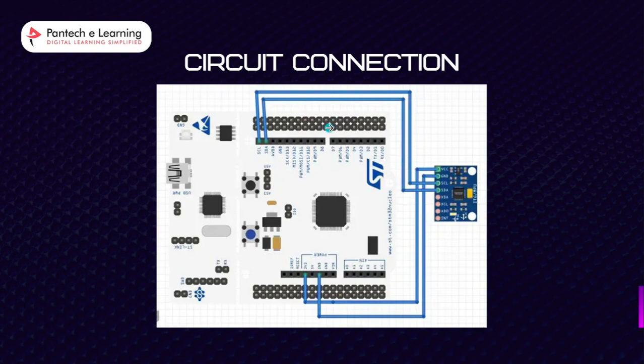And here I provide the circuit connection image. As we are using the STM32 Nucleo board, we just need to connect MPU 6050 VCC to the STM32 Nucleo 3.3V, ground to ground, and take the clock pin and data pin. You can connect them to PB8 and PB9, or on the board itself you will have clock and data pins, so you can connect directly to those pins also.